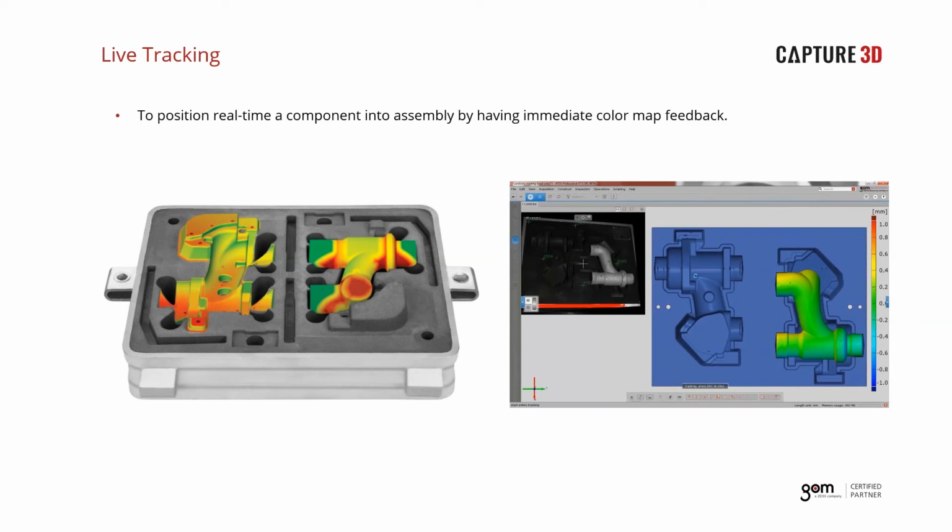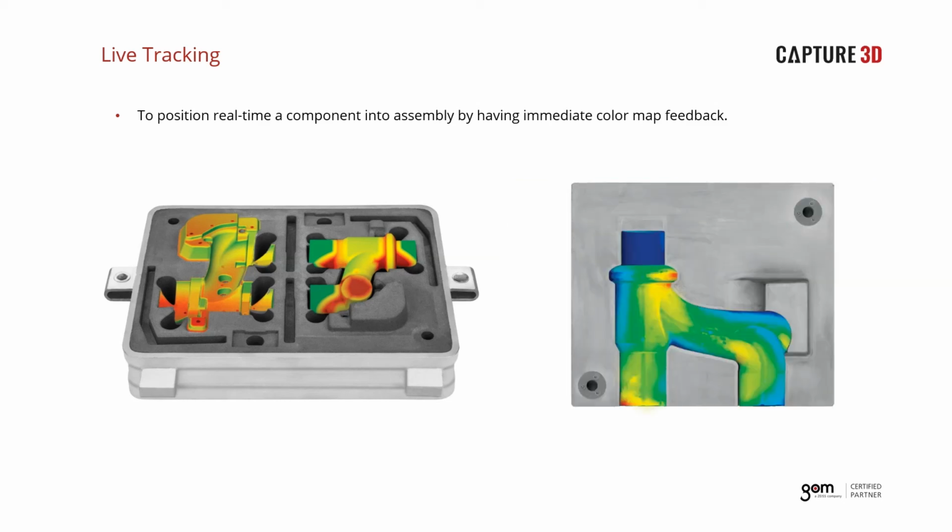Now, how is all this being tracked? It's using reference point markers, and you actually have to set up a component, which is real easy to do in the software. When those reference markers are near that component, you'll see a color map appear on your part. You can move that in that given area, and you'll get live feedback of whether you're in position, or even numeric values you can use as well, not just a color map.